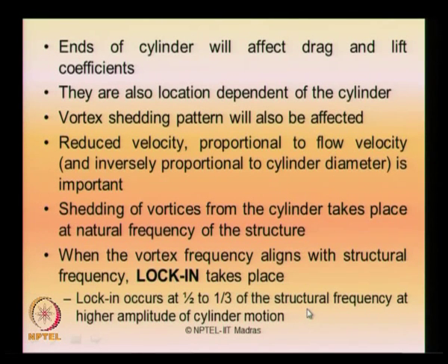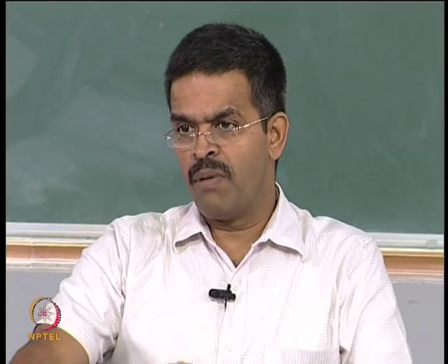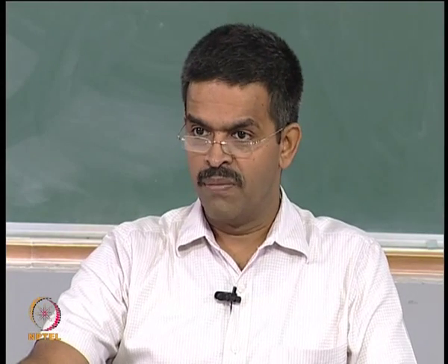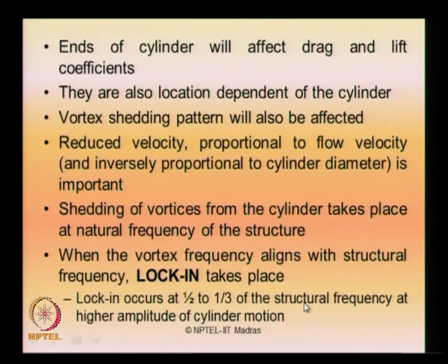So you can always have an impact caused by fluid induced vibration on the structure even at a frequency about half the structural frequency of vibration. This is true when the flow remains supercritical or transcritical, or at very high Reynolds number, where the lift and drag forces occur distinctly at different frequencies. So you have frequencies generated because of vortex shedding, which can create what we call lock-in phenomena, and there have been instances reported in the literature where members have failed because of lock-in frequencies occurring in the structures.